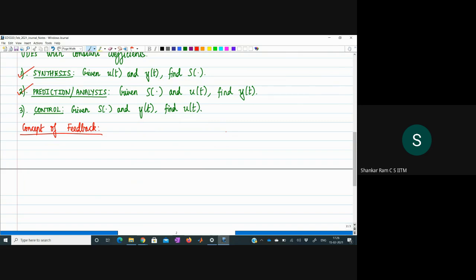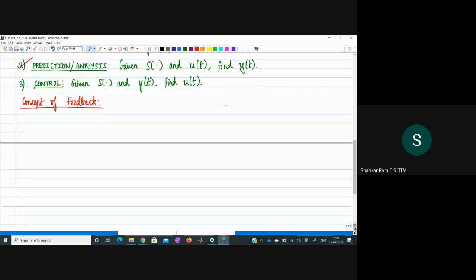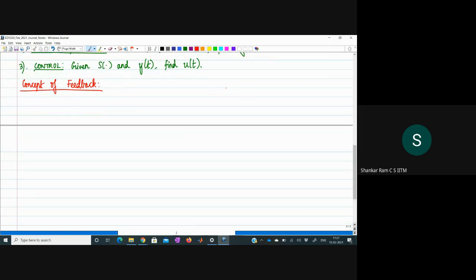So what I should do, first of all, is figure out that my car is oriented at 55 degrees, and I should feed this information back to a unit called a controller, which should then recognize that I am not along my desired orientation. It should say that there is an error between what is desired and the actual orientation, and then it should take corrective action. Okay, so that is the concept of feedback. This is very critical.